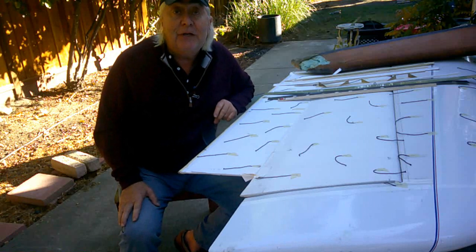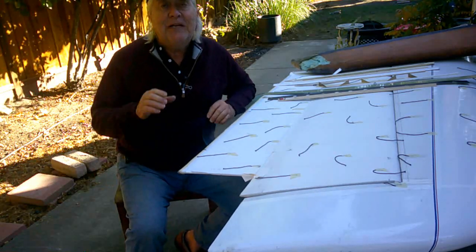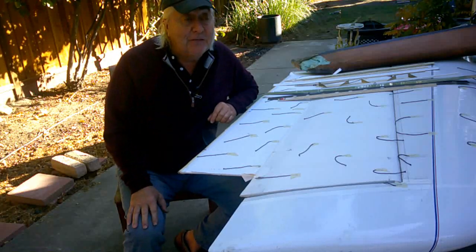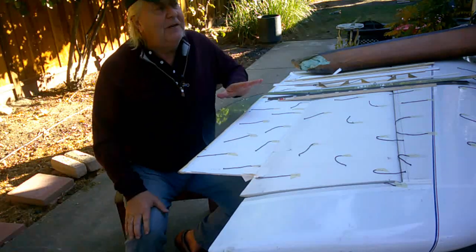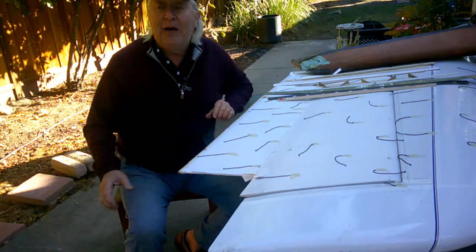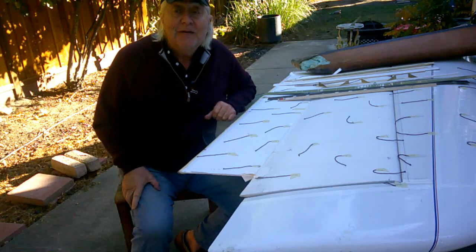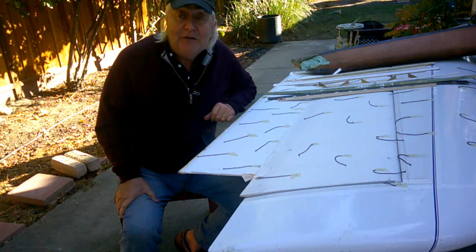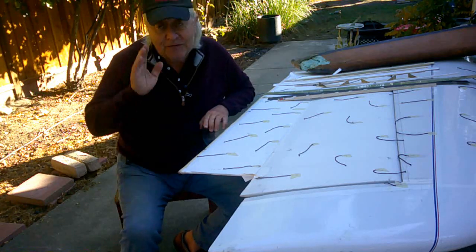So what do you do? You put in more aileron. It just makes the problem even worse. It's a divergent control system. Really bad. Happens very fast. So all of a sudden the nose is yawed off the wrong way. I'm no longer rolled. I'm flat. It's terrible. At best, you panic and you let go of the stick, and then the glider goes back to flying itself, and you just go straight ahead.